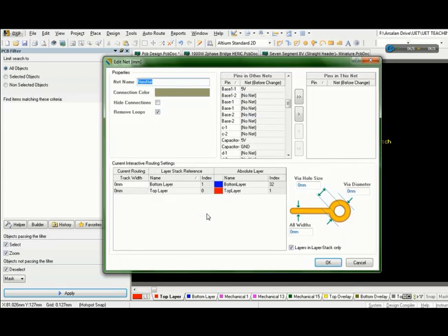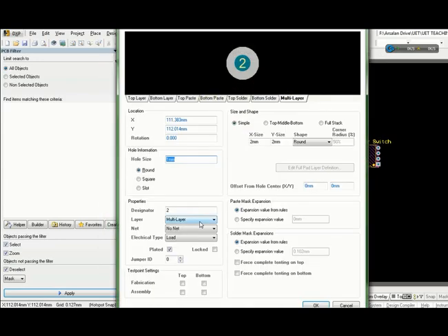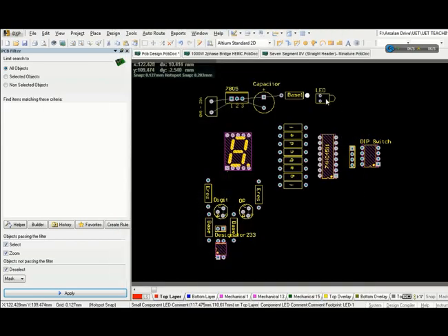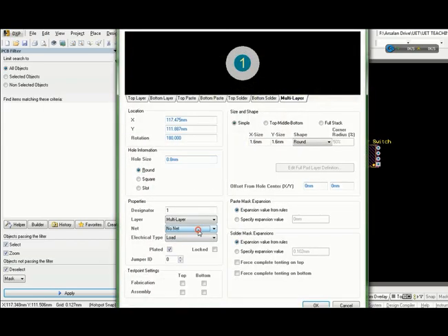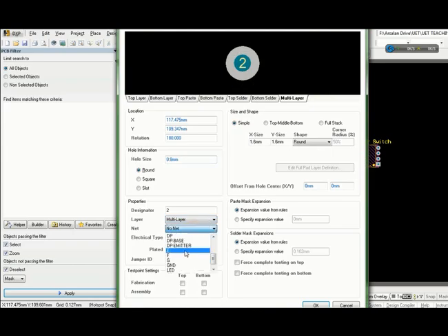So I'm just going to add some more pins. This is the LED, and then you can see this is the LED from where the LED resistor is going to be turned on. This is going to be 330 ohms or 470 ohms. The LED is going to be something red color or the green color or something like that.